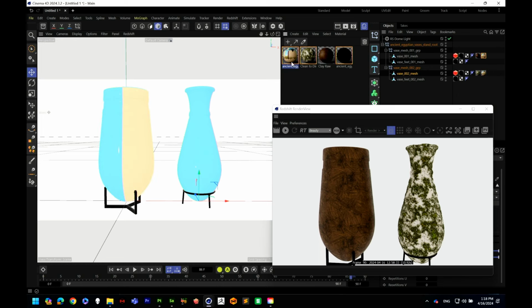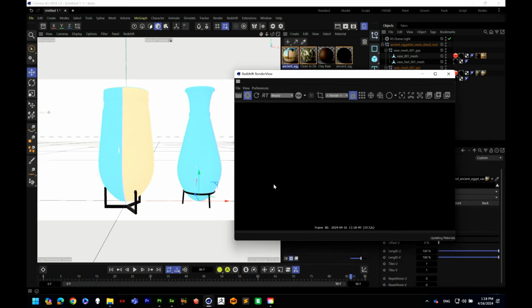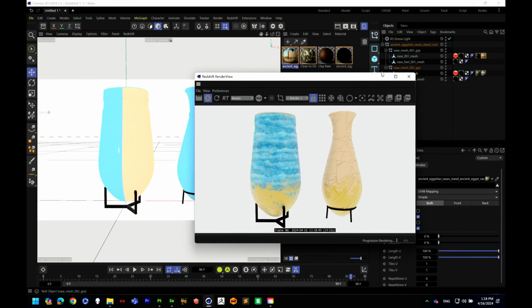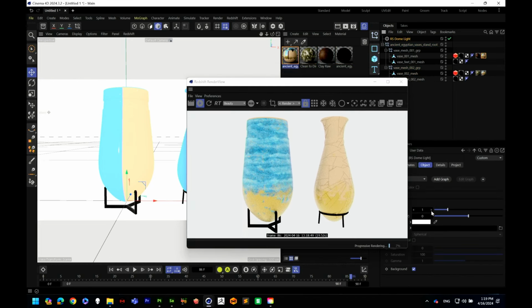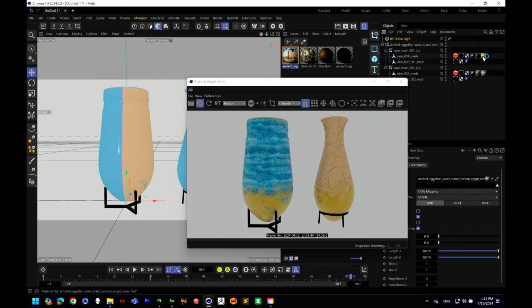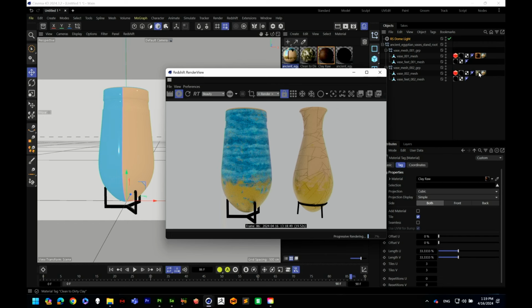Maybe it looks a little bit odd. Let's just double check that looks good here. We'll hit play in the render view, and we should be able to see our materials exactly as we had them before applied onto our model there. It looks a little bit bright, so let's adjust that dome lighting itself. Maybe do 0.5 on that exposure level. We can get rid of these other materials. We're going to dial the lighting in a bit, but those materials are here in Cinema.